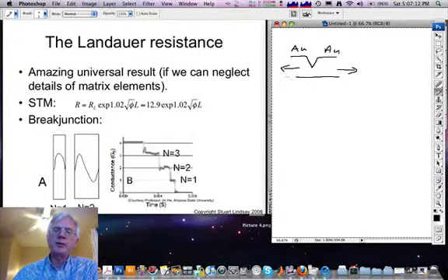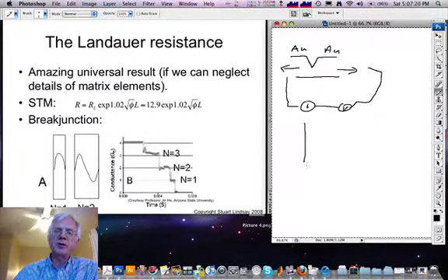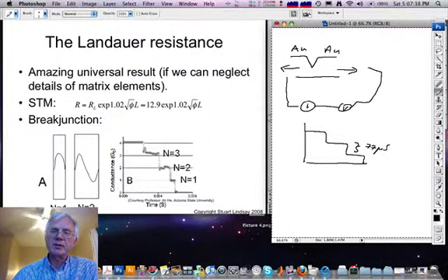As we pull this to pieces, while measuring the current through it at some bias V, what we observe, and real data is shown in this slide, is that the current drops in precisely equal quantum steps. And knowing the voltage, if we work out the conductance associated with each step, we see that it is indeed 77 microsiemens. So this is a demonstration that you can do with a piece of gold wire, a piezoelectric element to pull it to pieces, and then an oscilloscope to record the current. This might be current against time.